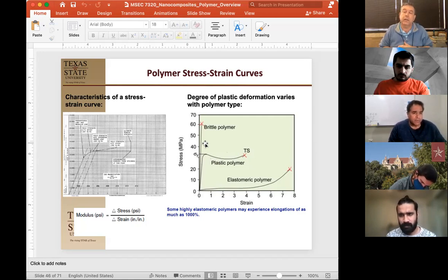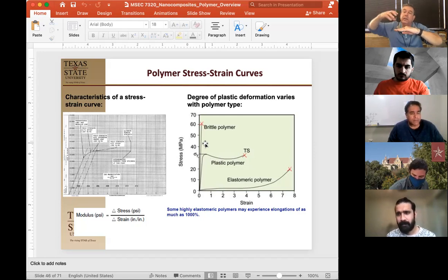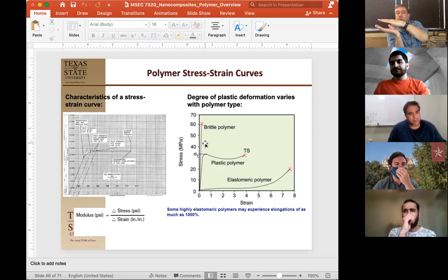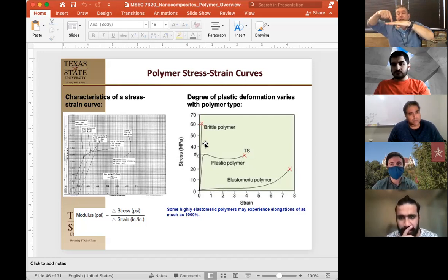Okay, durometer hardness has everything to do with how much force it takes to indent. So if you can imagine that, let's say most durometers are actually these little gauge things, and they have little probes. And what they're looking for is how much that probe, under certain amounts of force, can poke into that material. So we were looking at the resistance to flow with a backer. So the entire sample here is backing the resistance here.